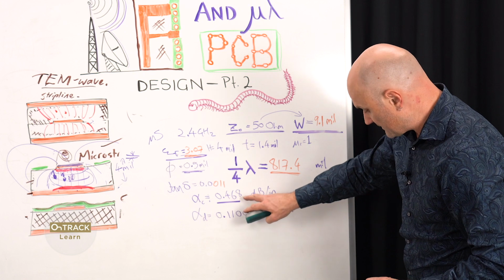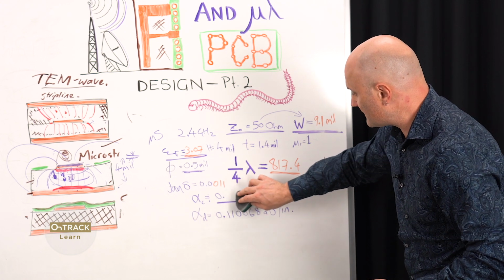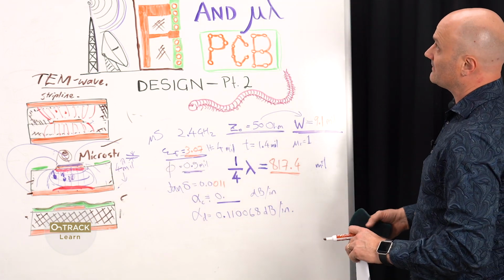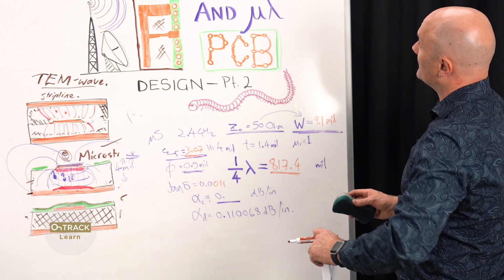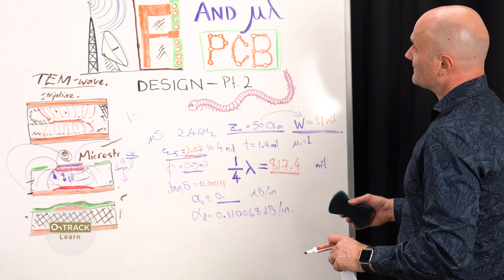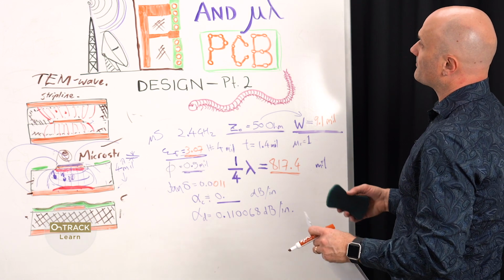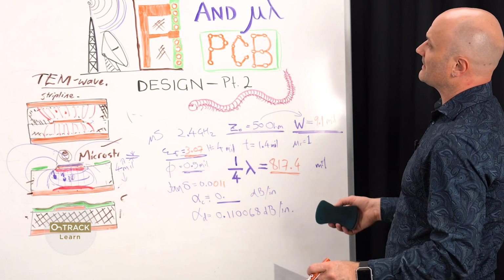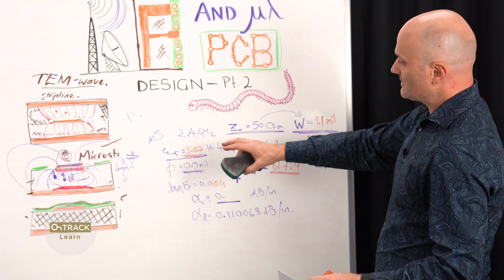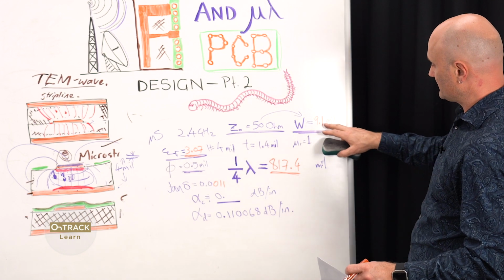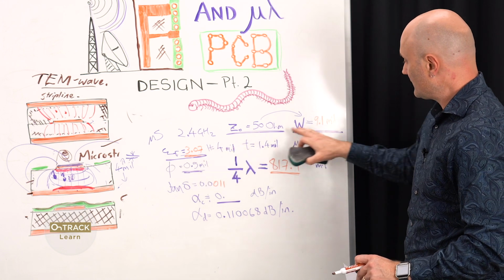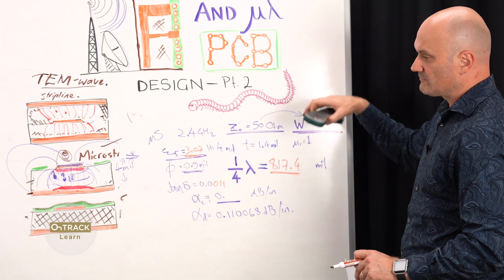The conductive loss actually lowers because the conductive loss is affected by the material in the dielectric as well. Conductive losses depend on the frequency of operation, the conductive characteristics of the copper, but they also depend on ratios and the size, because for the same impedance, the width got wider, and so the conductive losses drop.